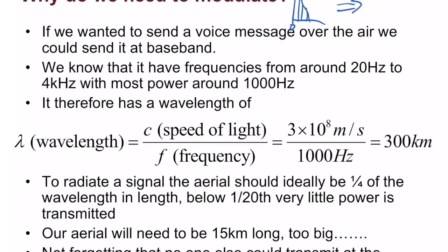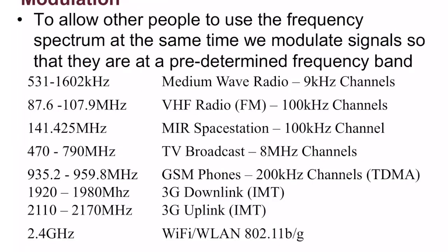And so what that's actually going to mean is that we shift those signals so they're no longer at 0, they're now centered at some frequency f. And so we'll go from something where we define our bandwidth on a single-sided basis, to now actually them being double-sided. And the process of modulation itself may also change the frequency components that are in our signal. So as we modulate our signal, whether it's transmitting it over the air or through optical fibers or sometimes on cables, we're going to change the way our signal actually sits.